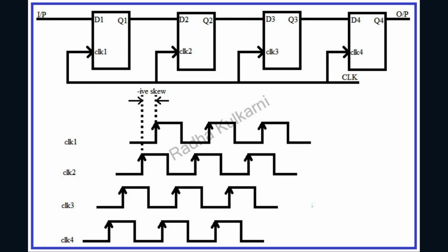However, because the clock at B is earlier relative to the data changing, it can sometimes help with hold time, making it easier for the data to remain stable long enough after that earlier edge. Wow. So it's this constant trade-off. Positive skew helps setup, might hurt hold. Negative skew helps hold, likely hurts setup. Exactly. Designers are constantly navigating this. It's a strategic balancing act, path by path, trying to meet both setup and hold requirements across the entire chip.